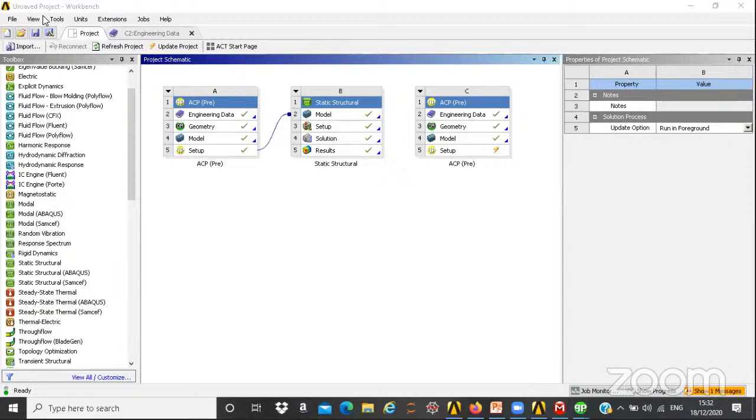When they simulate, we have to tell them that physically this kind of output is not possible. You can't have a feed of 20 or something. They don't understand the physical implications of how much feed rate or depth of cut will damage the tool. So we tell them they have to stay within these limits, because exceeding them would be dangerous. They also learn about actual machining systems in industry, which mechanical people know. Then we take their knowledge of control systems and try to have a kind of marriage between the two, so that in future we can have automation, some kind of Industry 4.0, and that too for composite materials.